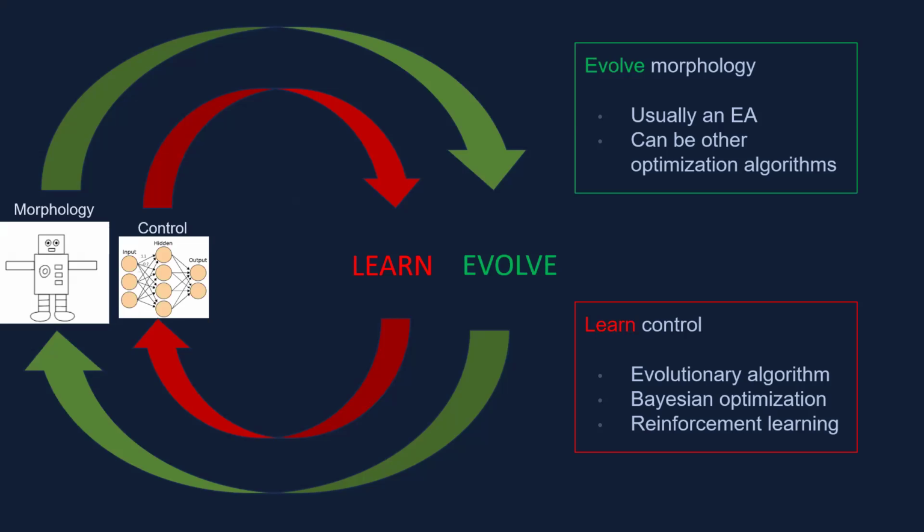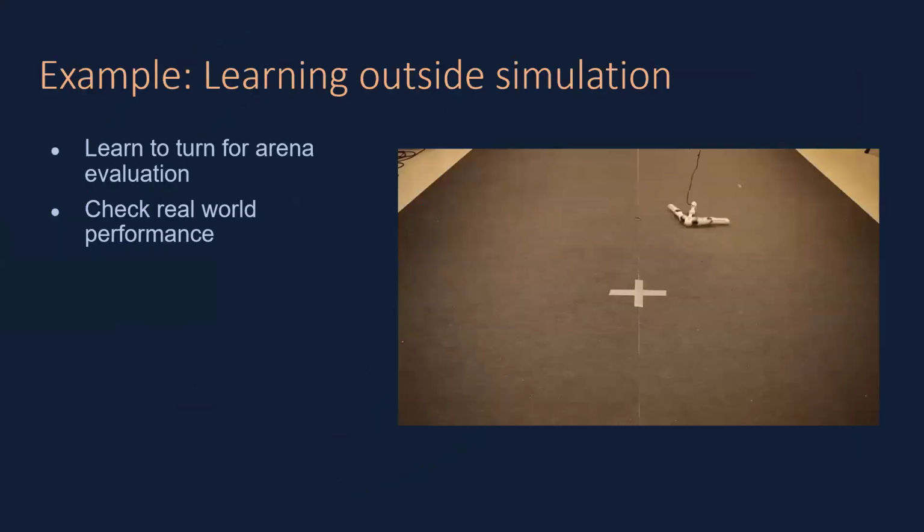Sorry, I'm still not clear how that helps with the selection of the new morphology. So in this evolution loop, there is this thing called survivor selection, and this selects the best out of the population of robots. So if you create, for example, 100 new robots, all these 100 new robots go through learning, and then you pick the 50 best. And you do that by the fitness value, which is the best performing out of those learning trials. Can I add something to clarify?